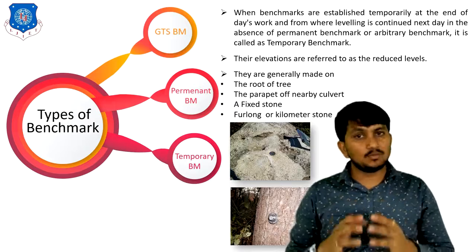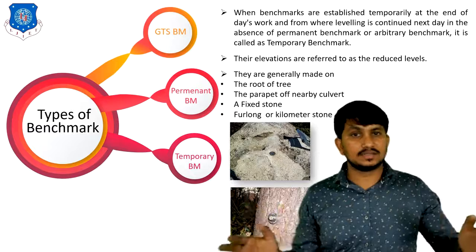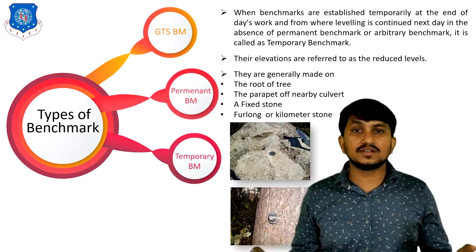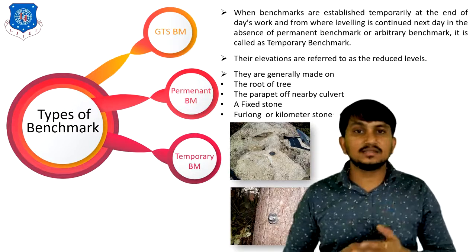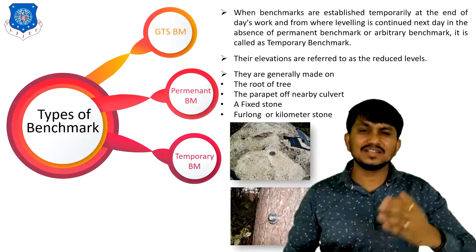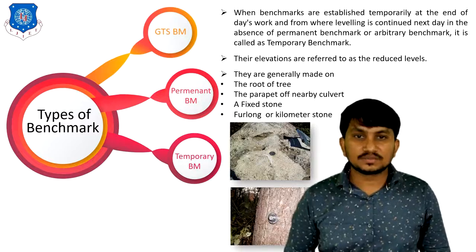These are used when the leveling is carried out over a long distance, like hundreds of kilometers. And hundreds of kilometers cannot be surveyed in a single day. So we have to establish a number of temporary benchmarks after the day's work for starting the work the next day. This is all about temporary benchmark.